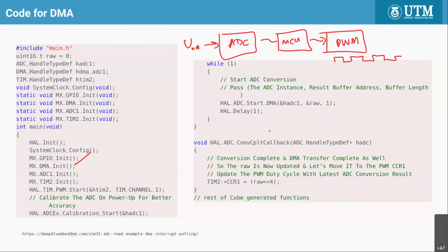So if you want to dim the display on your LCD, you will turn on the LCD for a very short time. So your eyes will average out. You will look at it and you can see that the monitor is dim. If you turn up the brightness, it will be like this, so longer time high and shorter time low. So this is the idea of PWM.